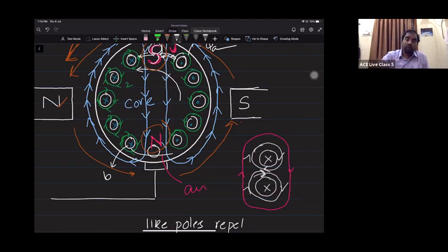Like that, with a hope this armature can align this south pole with the north pole, this armature will continue to rotate, rotate, rotate. So this armature is an innocent fellow. It doesn't know that there is a commutator cheating by changing the direction of current in those conductors and making that south pole reappear in the same place at every instant of time, and hence there is a continuous rotation of this armature. Is this point clear?